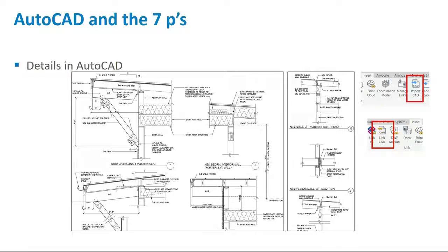If you are going to bring these in as an insert or an import into Revit, I'd really want to be looking at opening the DWG, purging everything, getting rid of everything that's miles away from the actual objects that we really want to work with. When I say purge, getting rid of line types, hatch patterns, all the stuff that's not going to work really well with a database, which is what Revit is.